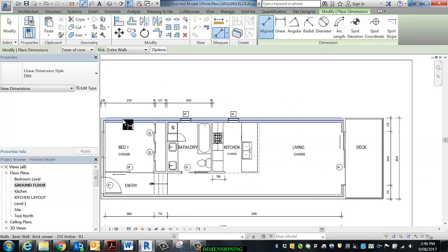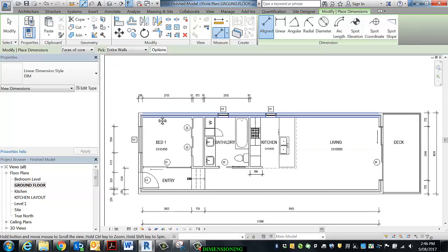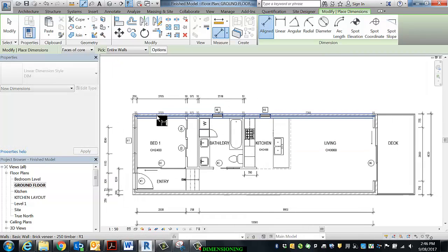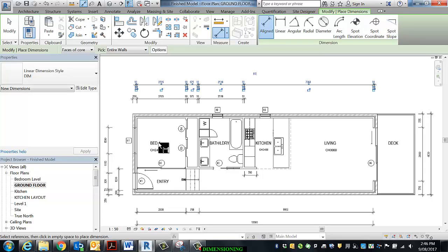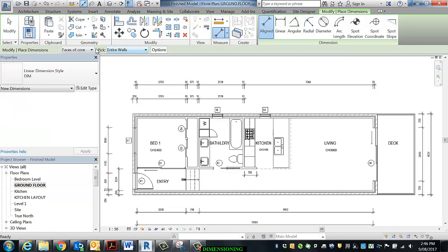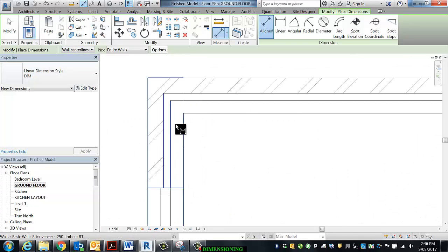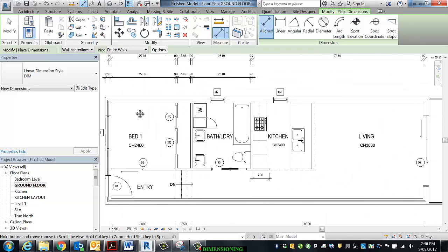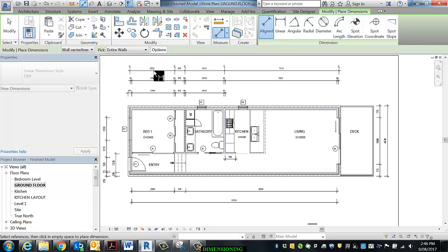Right, now you can see as I click this wall, as soon as I click the highlighted blue wall, watch what happens. You can see that the entire wall is, hang on, I've made a mistake. You see here that I've got 90 and actually want the thickness like this one to show. So I'm going to do that again. Actually, I'll leave that up there so you can see the difference. I'll change that back to wall faces because Revit understands through the way we've created this wall that this is the structural element and this is the finish. That's why that behaved like that. So I'll do that again. Sorry.